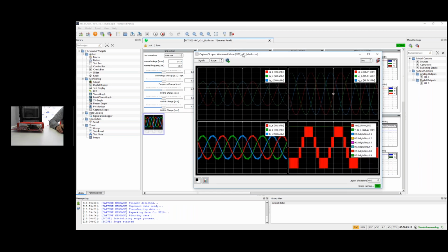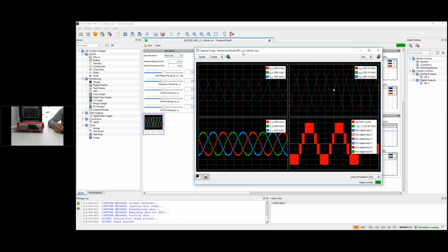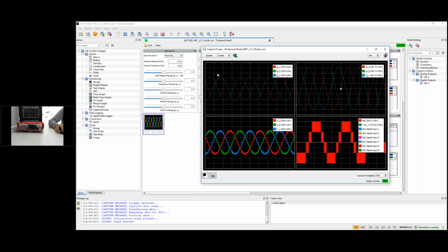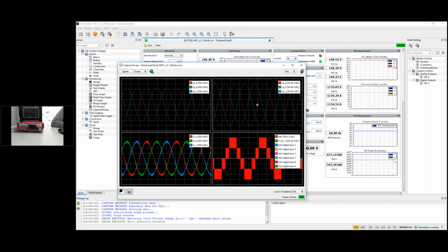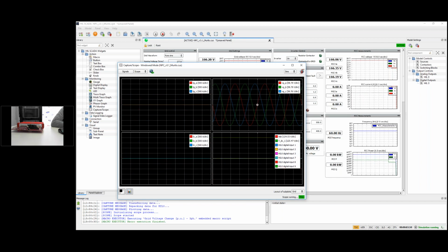Another thing that we have implemented is a low voltage ride-through specification. One of these specifications is that if the grid voltage is under 0.7 pu, it must stay connected for 10 seconds, and then it should turn off. So let's check it out. Here, let's turn this to 0.6. Let's wait around 10 seconds to see if currents go down. So here we have it, low voltage ride-through.